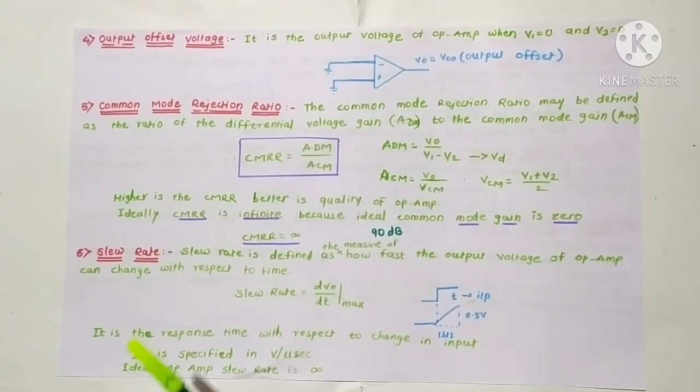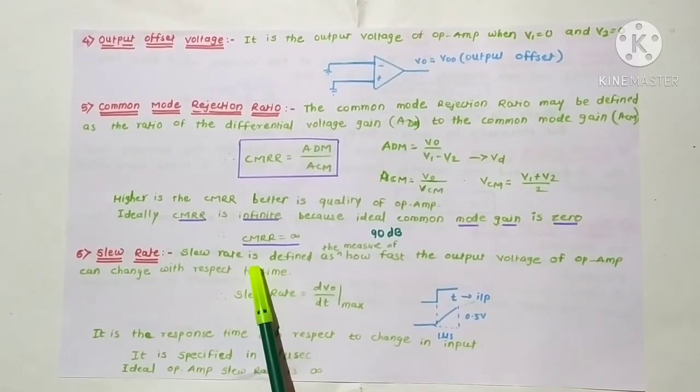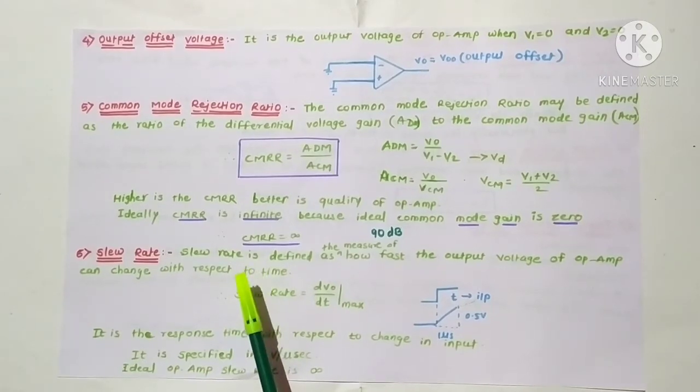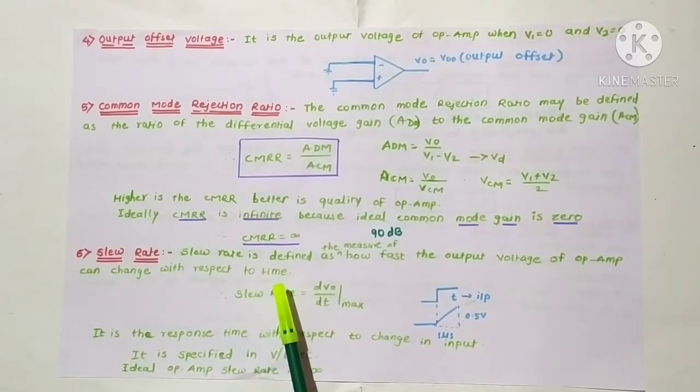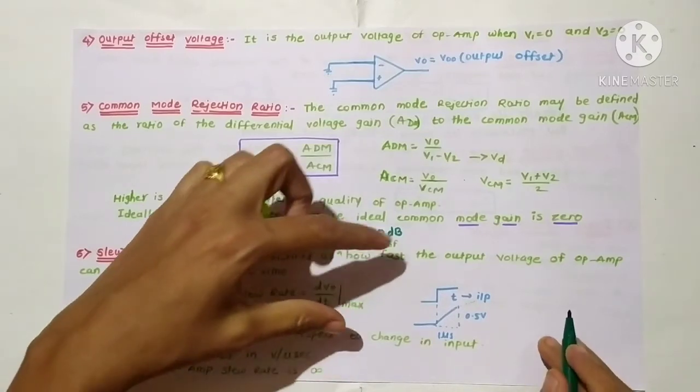This slew rate is the most important specification affecting AC operation. It limits the output voltage at higher frequencies. So if a sharply rising, overdriven signal is applied at the input of the op-amp, the output gets delayed, giving rise to a delayed feedback. Therefore, a distorted output is obtained, and you can see the distorted output in this way.